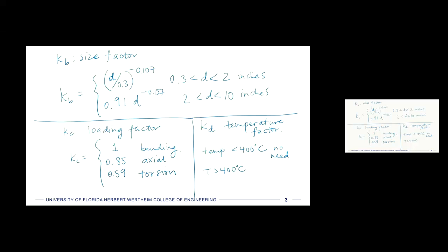And so we would say that this temperature factor is a factor applied to the endurance, a factor applied to how those properties are changing compared to room temperature. So we take whatever's happening at room temperature and then multiply it times something. And it's a function of the temperature. So I'm just going to write the equation here. So it's kind of this factor of at temperature divided by room temperature, and it's a function of the temperature itself.